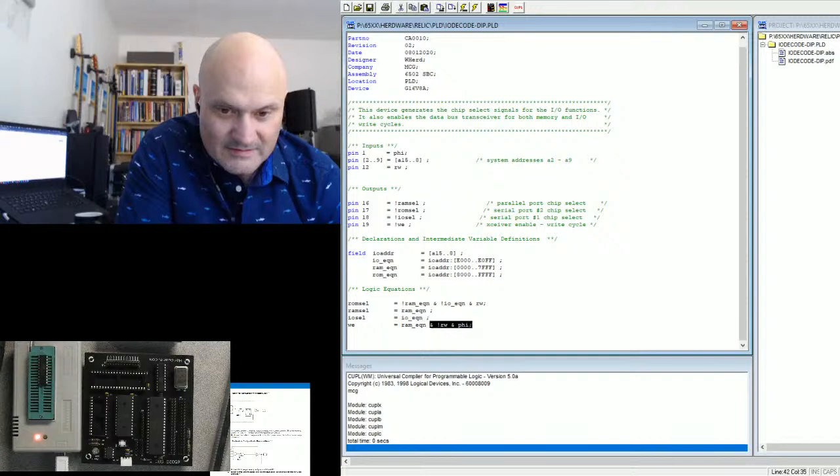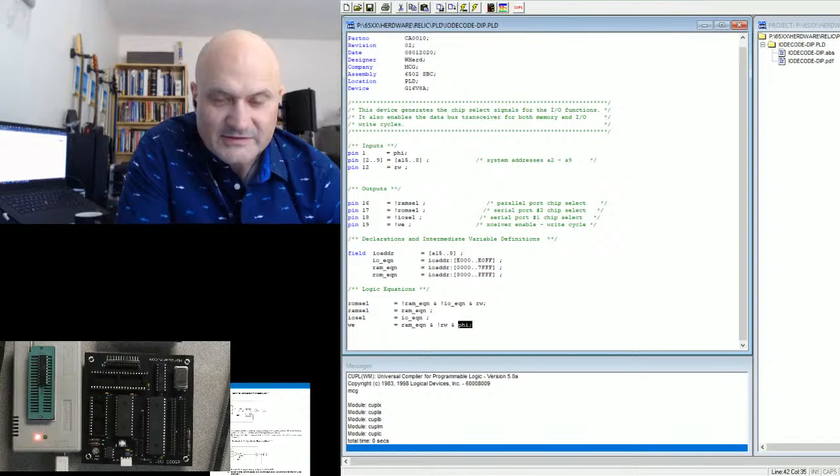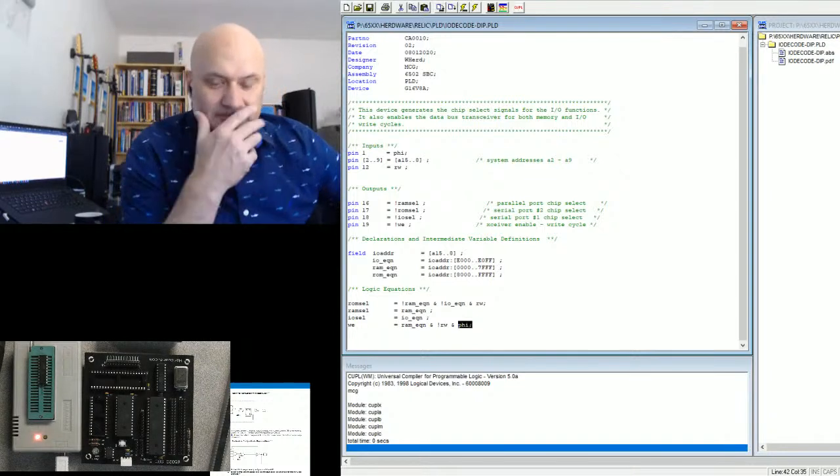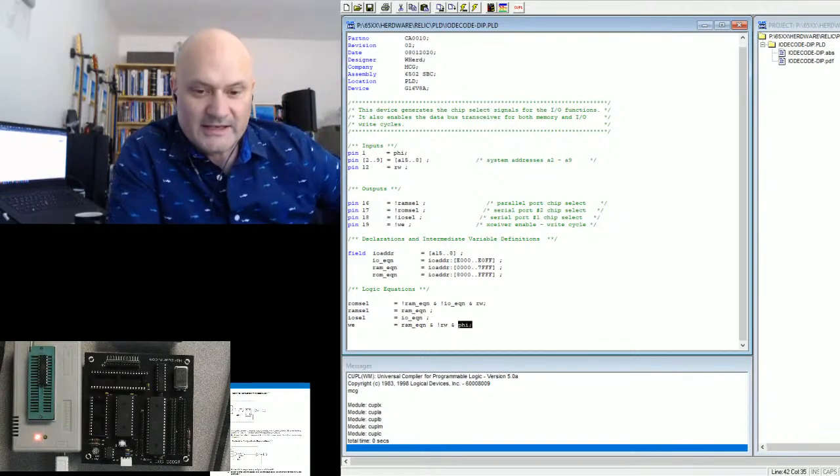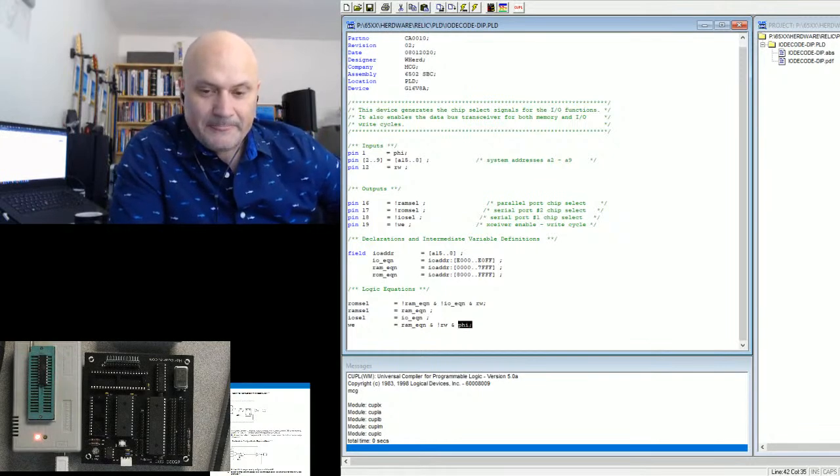And the read-write strobe says, well, okay, first off, we're only going to strobe it on a RAM. So we qualify with RAM. Yep. We're only going to qualify if the read-write line's low, and we're going to do that with the clock that we said, the phi, that says, okay, it's valid. All right. So that's what you call a gated clock. Yep.